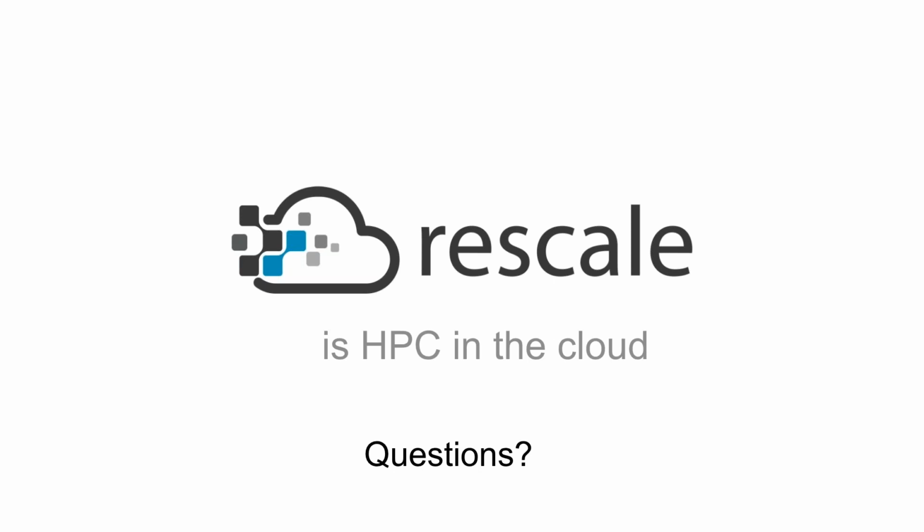That makes things as straightforward as they can be. However, also in the past and for other versions, we were able to run post-convert directly in batch. So you didn't have to open Converge Studio and prepare your jobs for the post processor. You can do that automatically with the command that you're running your simulation.